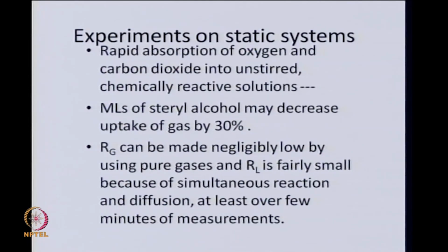So, we are talking of mass transfer and chemical reaction. It turns out that a monolayer of stearyl alcohol can reduce the uptake of gas by as much as 30%. So, solute transfer from gas to liquid can be significantly reduced if you have certain monolayers like stearyl alcohol.